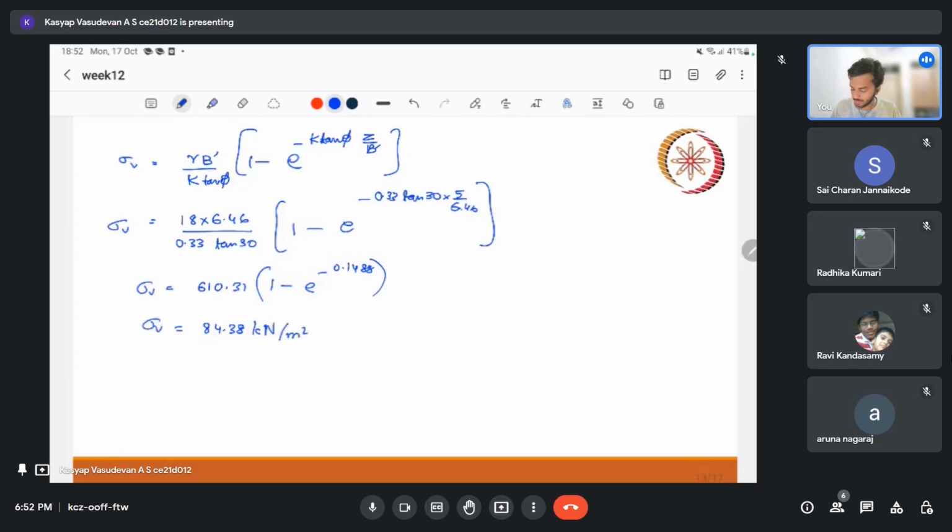So we get the stress, the vertical pressure acting on our tunnel's upper face. So we can now design. If you tell the structural engineer, or if you look at the available cross sections of different linings, tunnel linings, if it is a conduit, we can find the manufactured cross section. If it is a tunnel lining, we will have to design the cross section. While designing the cross section, we will need this particular value, that is our vertical stress acting on it.